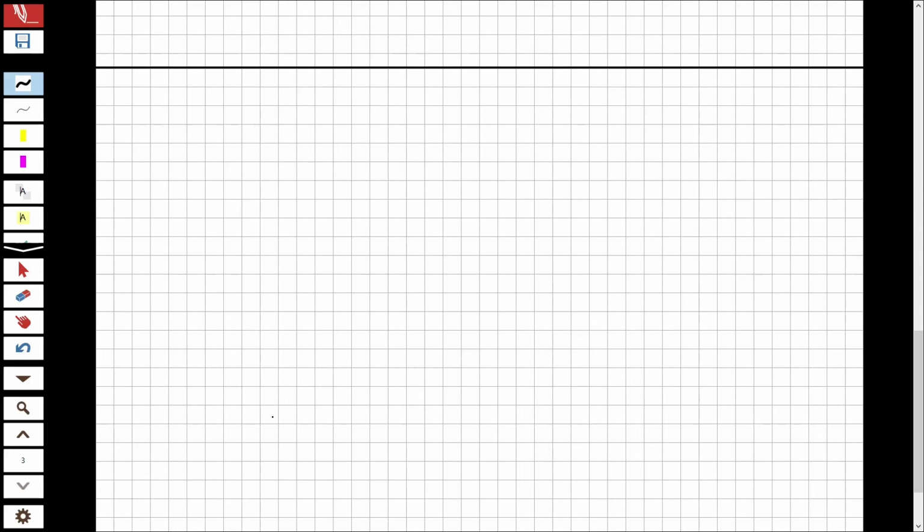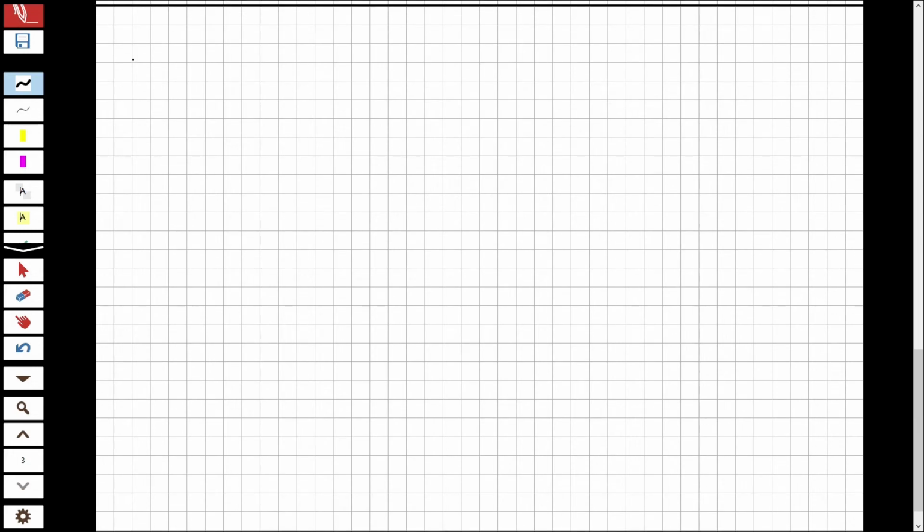I'm going to draw them here. Start with the shear diagram. I'm going to draw them all separately. For now I'm going to raise up at A. What I have at A as a shear is 25.2. So I'm going to decrease as 48, and because it's distributed, it's going to be something like that. And this is going to be 22.8. For the first part, this is A, this is D.